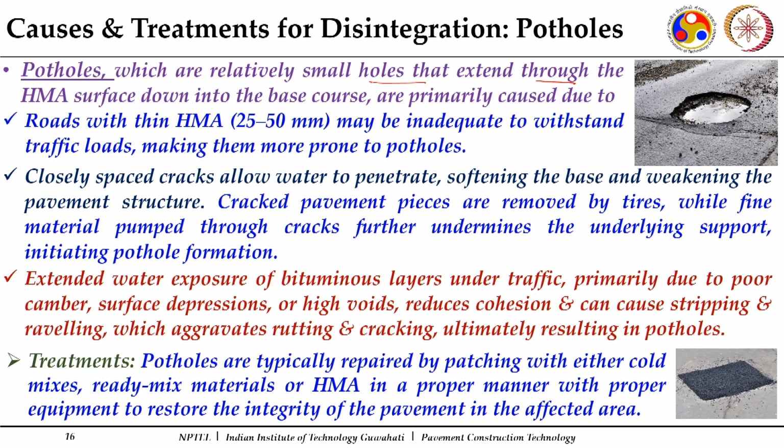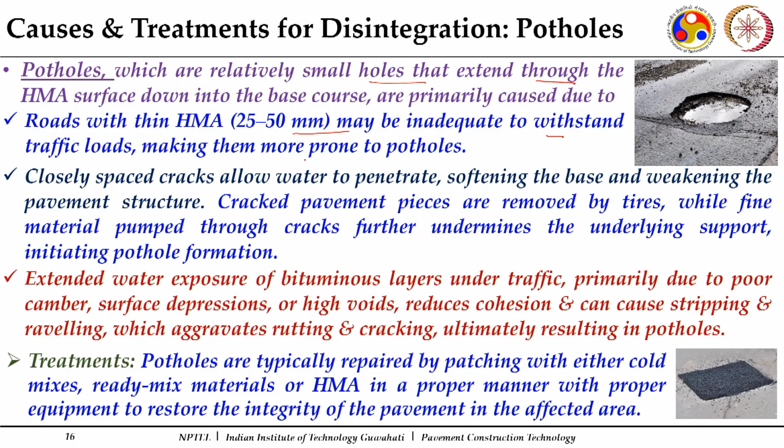This usually happens when you have thin HMA overlays. This is a very frequent problem which we can see in MDRs or other categories of roads which have only a thin HMA layer to withstand quite heavy traffic loads. In that case, those layers experience cracks, and very frequently pothole formations also.